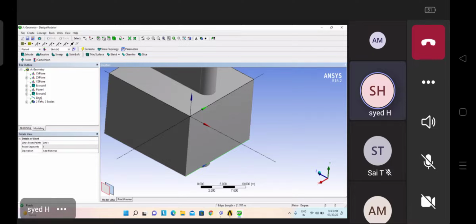And here you can find that the line has been created, and under the Part Body it is also showing the line body. Remember one thing: whenever you import this model and open it under the model environment, where we assign the boundary conditions, whatever things are visible here in the part and bodies option, all those things will be visible to you under the model environment also. That is the reason we will make this a body. We will make the sketches a body, so that we can assign the boundary condition to the lines.